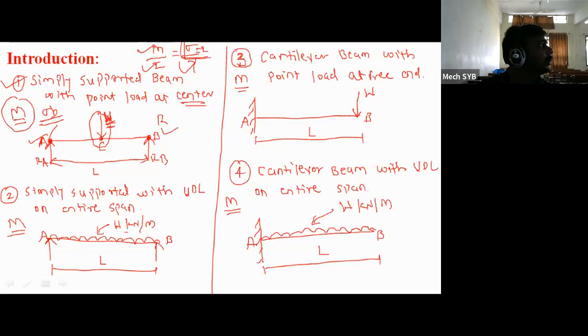So that is the procedure we have to follow to calculate the bending stresses in the beams. And how is it to be calculated? By using this. So here shear force calculation is not required. In a bending stress calculation, shear force and shear stress calculation is not required. And one statement I will tell: while calculating the bending stresses in the beam, the effect of shear stress, the effect of shear force is totally neglected.